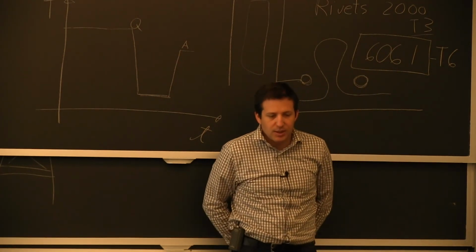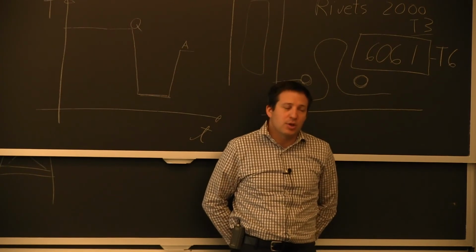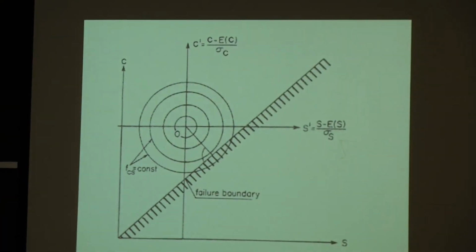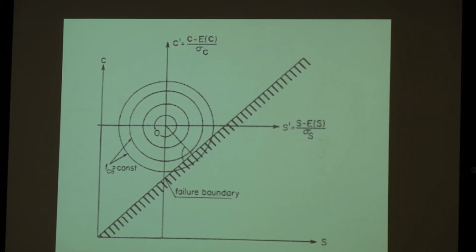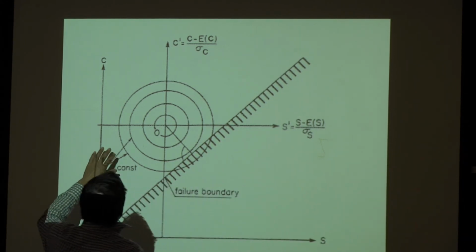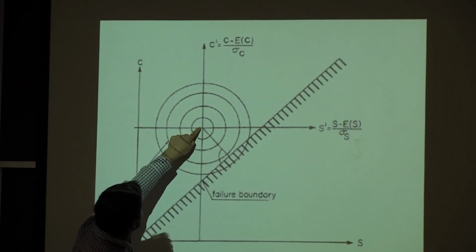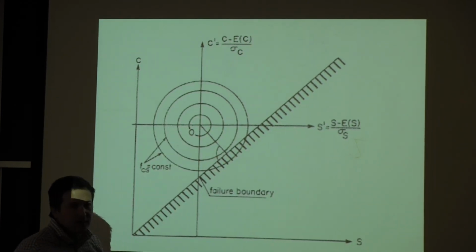This was a section that I created about another completely different way to look at factor of safety. It's essentially a statistical way. This is the reference. And the idea is, if we're looking here at the demand and the capacity, there's some variation in both of them. And when we're talking about working stress, for example, that would be the point right here. So higher capacity, higher stress, this is the failure boundary. So you put your margin. In this case, it looks like we have about a 1.5 factor of safety.